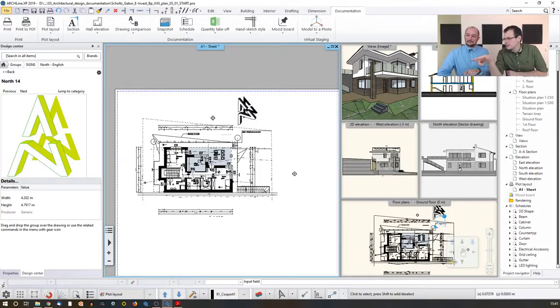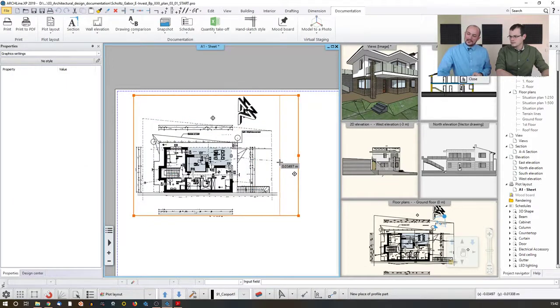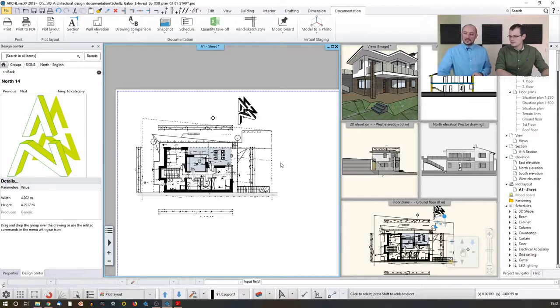Another important thing is that on the right hand side we see another elevation symbol. I don't want to modify that on the drawing, but I want to make it disappear on the layout, because I don't need that. How do I do that? Well, you can actually put it on a layer. That's also a solution, but what I'm willing to show you is that you can actually crop the contour. So when you select this virtual view of that original content, you can just click on the edge and say that I would like to offset that, and I just keep that part. And this happens the other way around as well. So when you made something smaller and then the design changed and it became larger, then you don't need to replace it and remove it and place it again, but you can just modify the contours of the existing one.